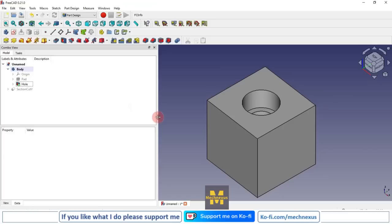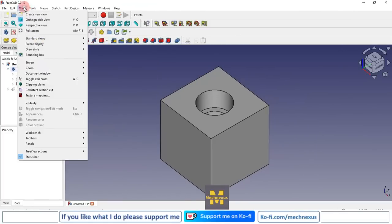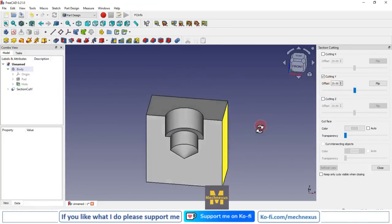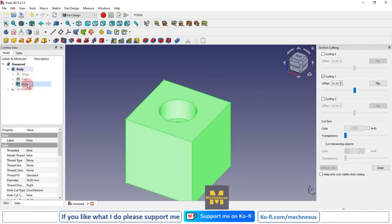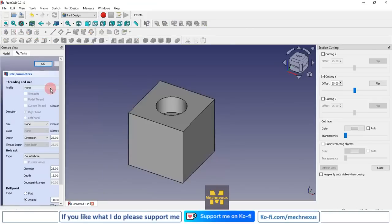And now we will see our counterbore hole by taking the sections. So go to the view and click on persistent section on the Y-axis. So you can see that a counterbore hole is created. Now let's turn it off on my body, and now let's try some different hole profile.